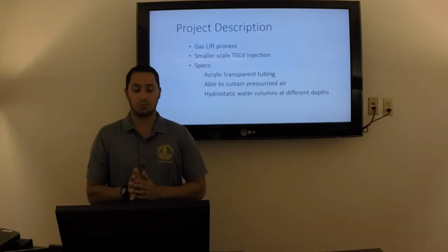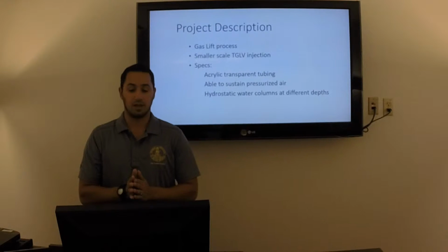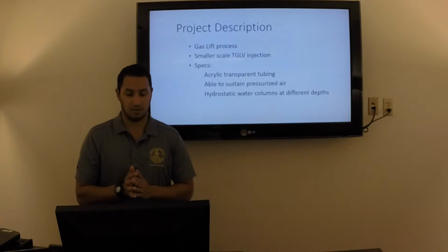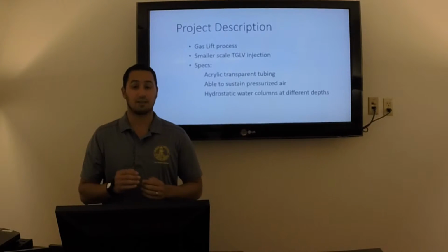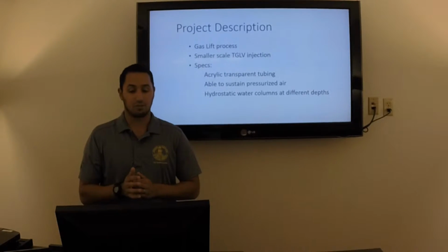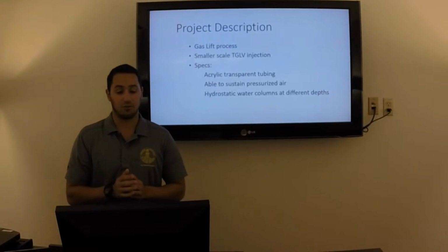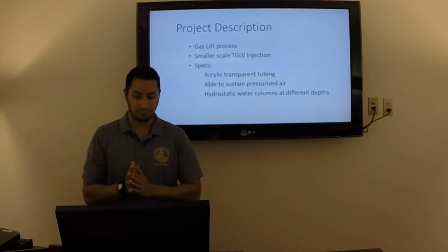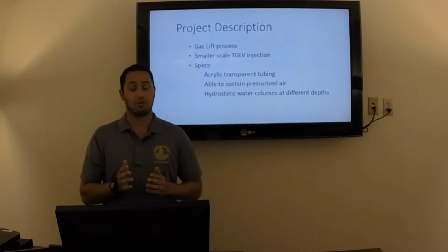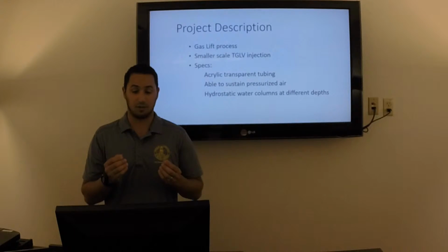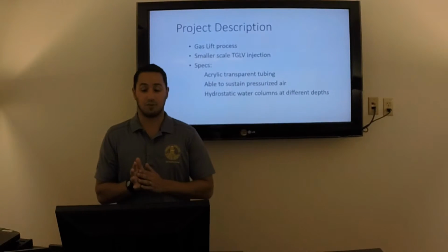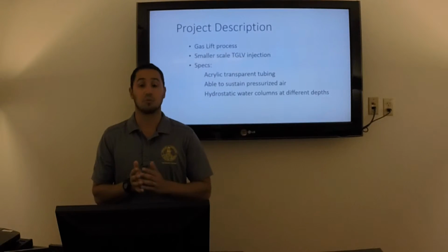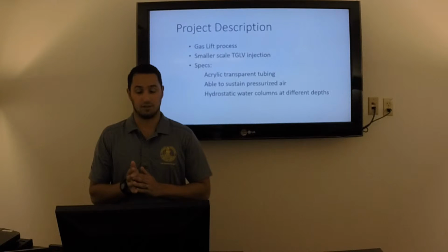As the gas enters the tubing string through the valve, it creates an aeration or bubbling effect in the liquid column. The gas bubbles expand as they rise to the surface, displacing the liquid around them and reducing the density and weight of the fluid within the tubing. This decreases the flowing fluid pressure, creating a differential pressure between the reservoir and the wellbore and allowing the well to produce at its optimum rate.